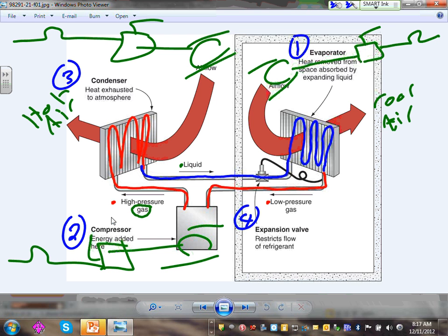So that's the principle of operation. Now this could be your air conditioning, guys. If you have home air conditioning, here's what happens. The evaporator is inside your furnace, and the blower is blowing right through it. Then the compressor and the condenser are in the outside unit. If you ever stuck your head right above the furnace fan, you'd feel the heat coming out of it. That's how they remove the heat from a house or a building.